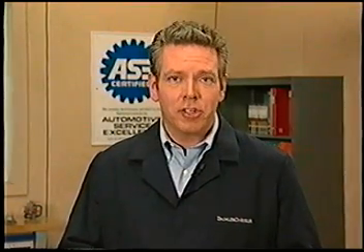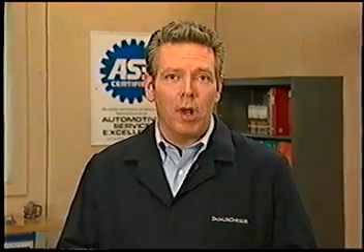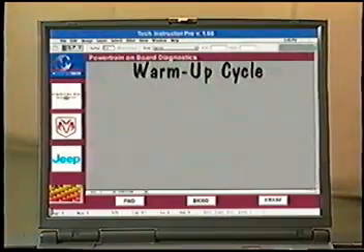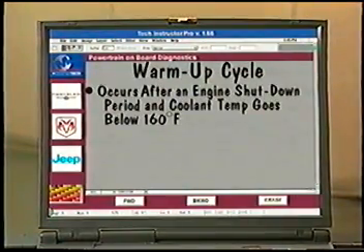In general, a good trip is considered complete after the engine is started and failed monitors have been rerun. If there have been no failed monitors, the trip is complete after the O2 sensor monitor and catalyst monitor have been run. After the MIL goes out, the DTC and freeze frame data will remain in memory until 40 warm-up cycles have occurred with no recurrence of the fault. After 40 warm-up cycles, they will be self-erased. A warm-up cycle occurs after an engine shutdown period when the engine coolant temperature has fallen below 160 degrees Fahrenheit.